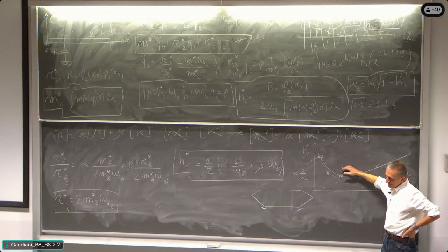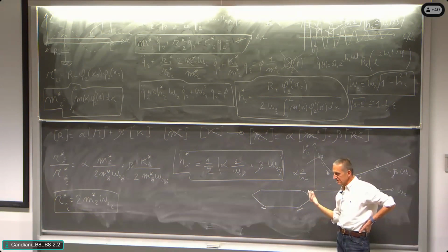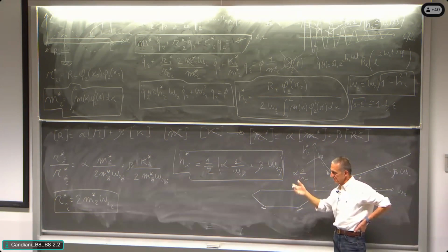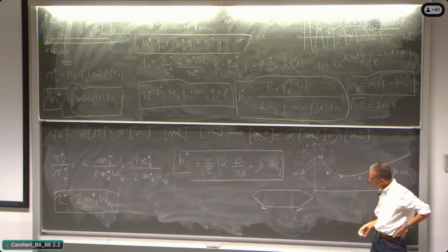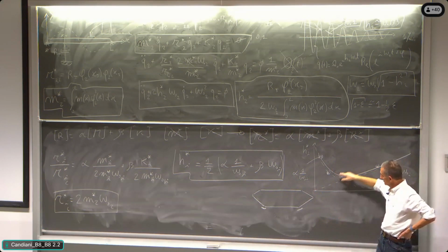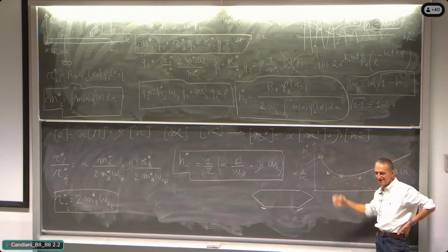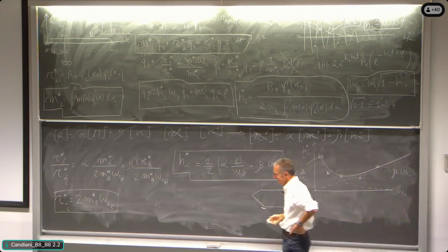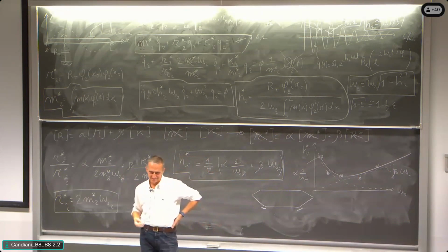So in all the cases where you look at malfunctioning of big structures, typically due to excitation by vortex shedding, not buildings, big structures with higher modes, typically the VIV of very long span bridges is happening not at the first modes but at the higher modes, the 3rd, the 4th, and all of that sounds in agreement with the damping discussion. Mr. Taylor is happy because of that, all right?